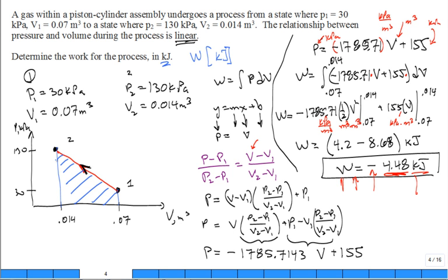It's a straight line curve. It's a triangle, so you just get the average. Conceptually I can cut right here and take this part, flip it over and put it there. And so graphically, the work is just the average pressure times the volume change.